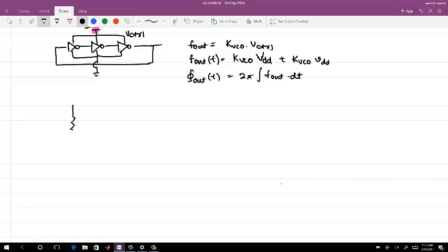I have this resistor, I'm going with the pseudo differential, right? This is VDD, and let's say we are keeping the current. This is Vin, this is Vout. In all these differential cells, whatever I is flowing, let me call this Iout, that has a linear relationship with respect to gm, right?